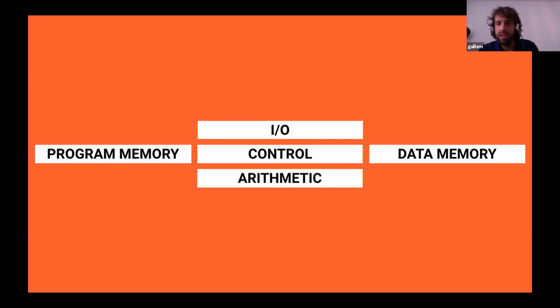And you will ask, what's the role of the data memory? Well, usually the program memory we won't be reading every time. We'll move the program into the data memory, and use data memory as a way to store temporary values, as for example, how many milliseconds have passed since the last time that we checked, to keep counting till 2000.